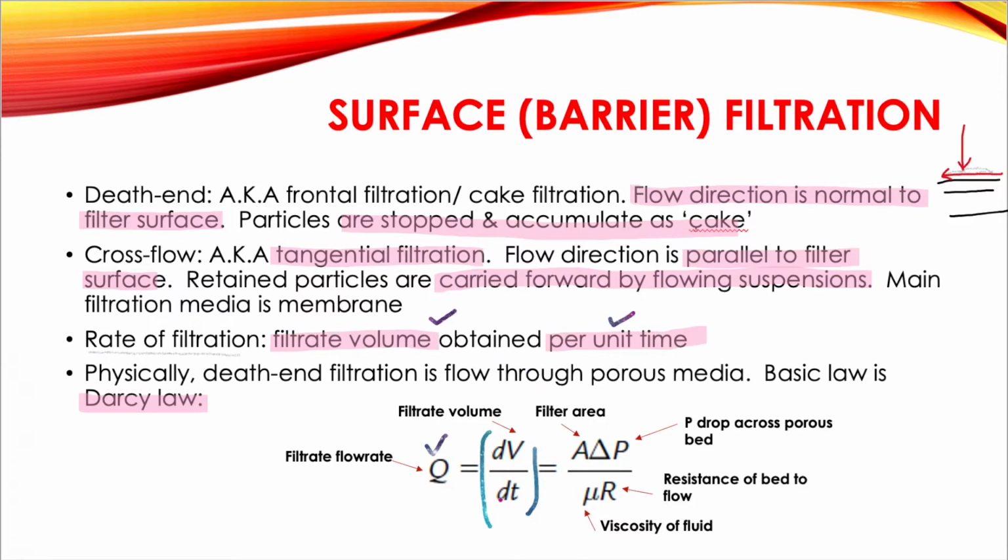So dV/dt equals the filter area times the pressure drop across that porous bed or filter, over the viscosity of the fluid times the resistance of the bed to flow, because over time the cake will build up at the surface of the filter, hence creating a resistance for the flow to pass through.